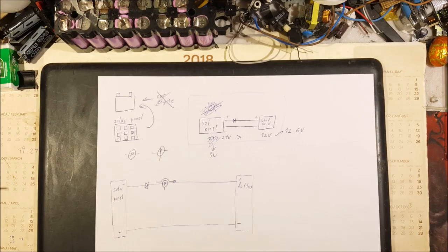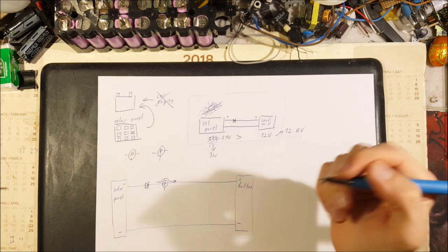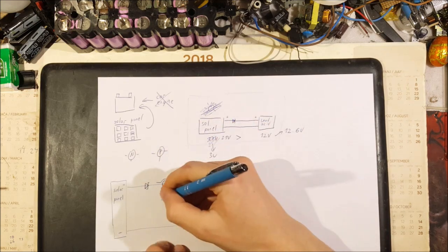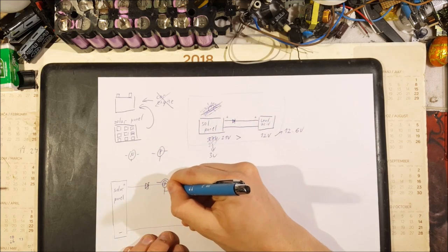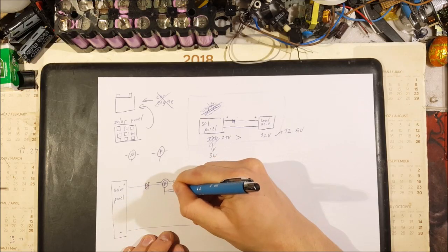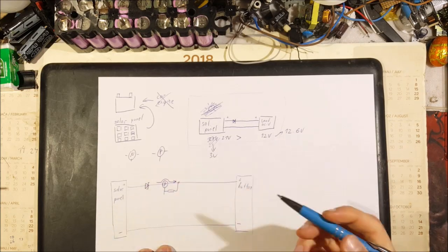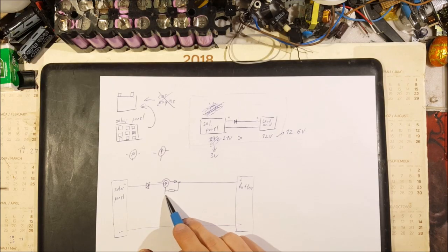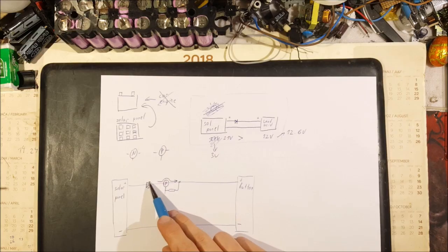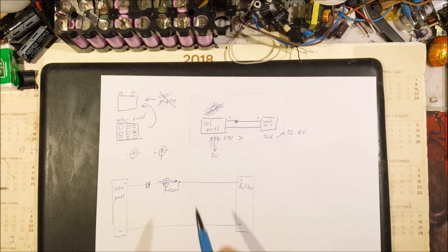So the simplest way to drive a P-channel MOSFET like this is, first, let's add a simple pull-up resistor to the positive rail, meaning that if there is nothing else pulling this wire down, our MOSFET will always stay open, meaning that there will be no current flowing through it.